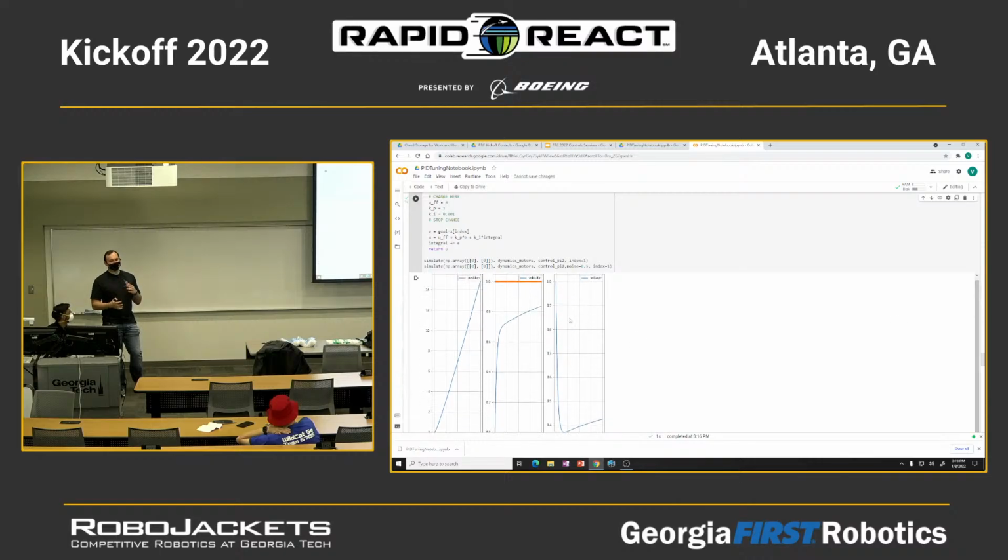So this is the concept of a PI controller, and they're really good for holding an actuator at some fixed location, because it'll handle any of that steady state error of it not quite reaching the correct height, but being pretty close. Due to gravity, yes. Any questions? I lost you completely. Feel free to stop me and ask questions.